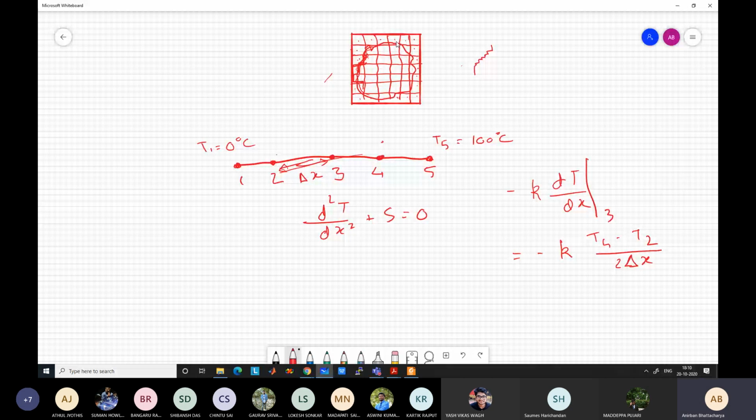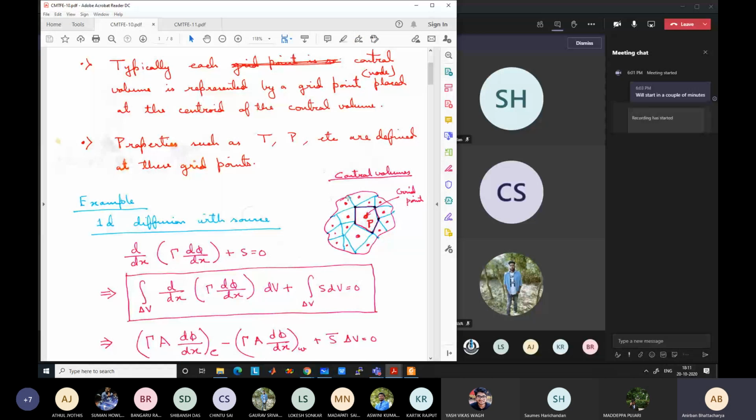Whereas using finite volume, you can put any arbitrary control volume near the interface. I can put very small control volumes near the interface with arbitrary shape, like arbitrary triangles, so that they almost follow the path of the boundary. I will not put a curved interface, but we can put small triangles so that they almost follow the path of the boundary.